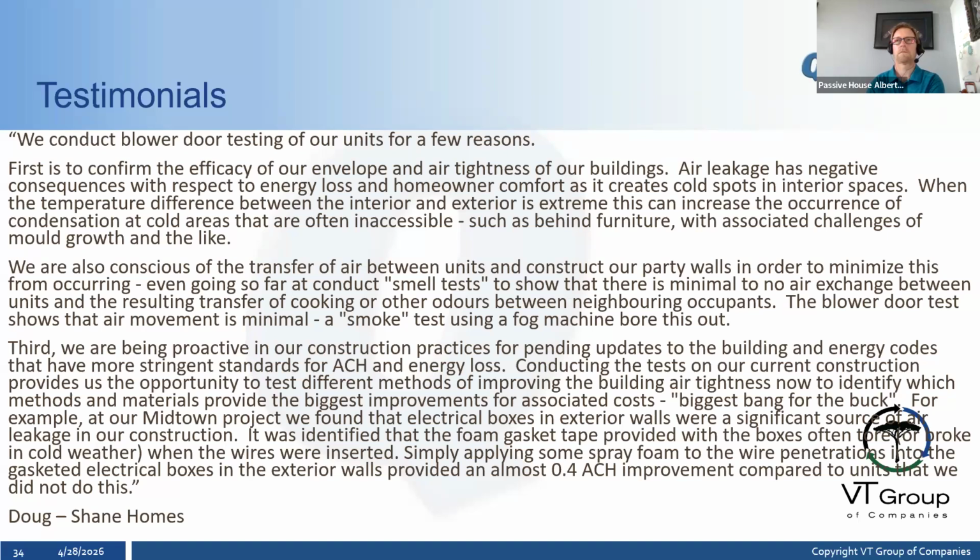By that, what I mean is at least 25% of that building is exposed to another building of approximately the same conditioned space, right? If we have an end unit, the unit it is attached to is also going to be roughly 18, 19, 20 degrees throughout the year, just like the primary unit is. So it's not an energy loss issue as much as it is a comfort and odor tracing kind of thing. We've done testing on an attached house where the duplex owner on the left could smell what the duplex owner on the right had been cooking. So that's a comfort thing rather than an energy efficiency thing, right?